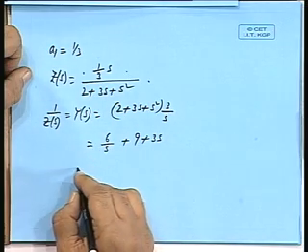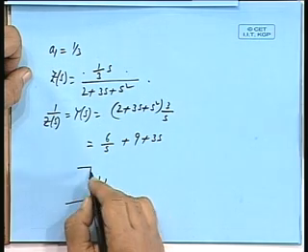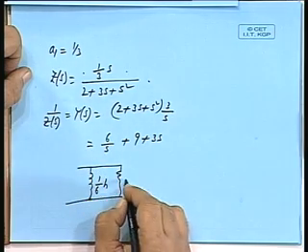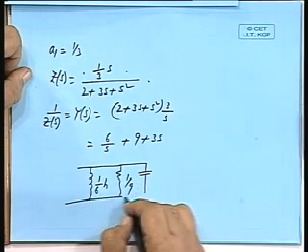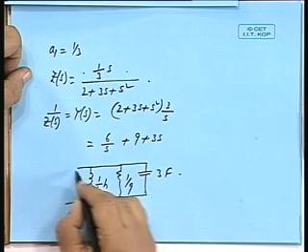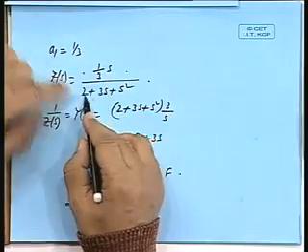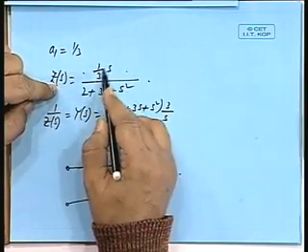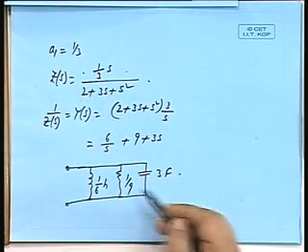So this is an admittance of what? 1/6 Henry, 1 by 9 ohms, and this is 3 farads. So this is basically the network, is it not? So don't get frightened even if there is a single term here and there are 3 terms here, because it is in the center. So if I just divide, I will get basically RLC, I will get Zs. Is that okay?